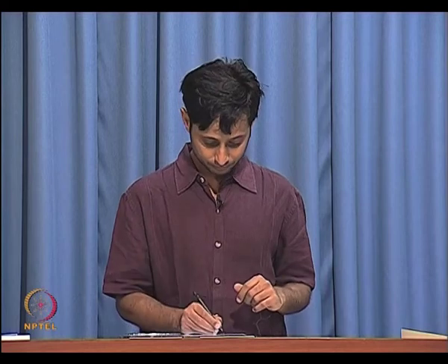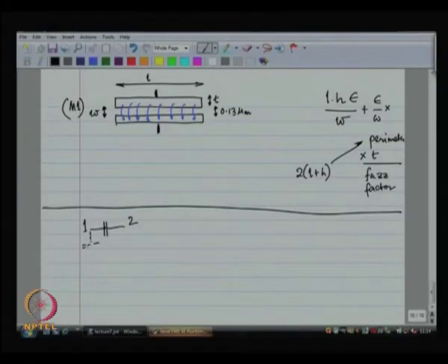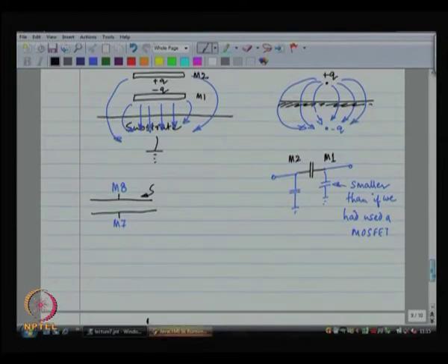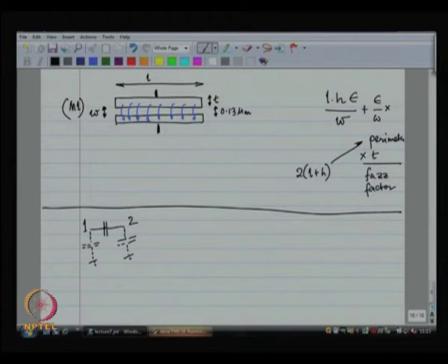So, beware that they have parasitics to ground. As long as you are aware of that, you make your design. In the earlier cases, metal 2 had less parasitic to ground than metal 1, metal 8 had less parasitic to ground than metal 7. Fine.